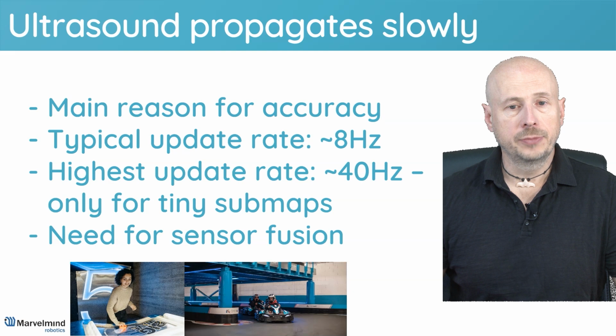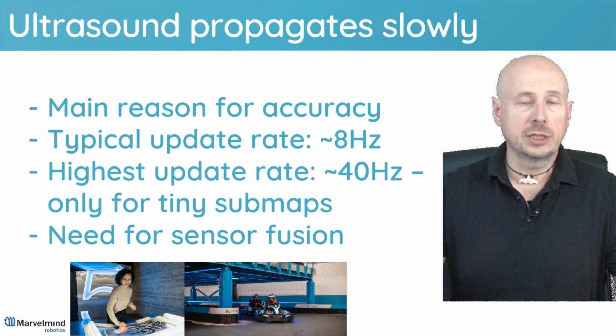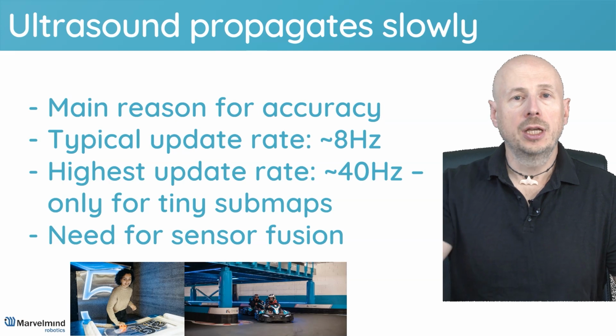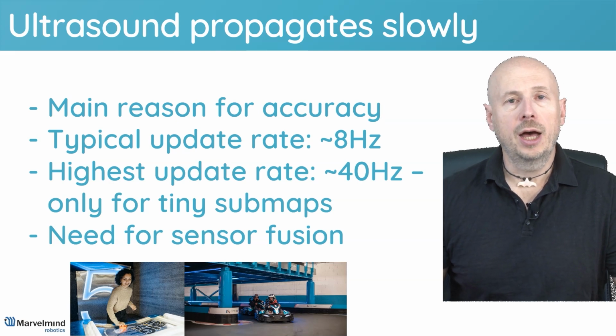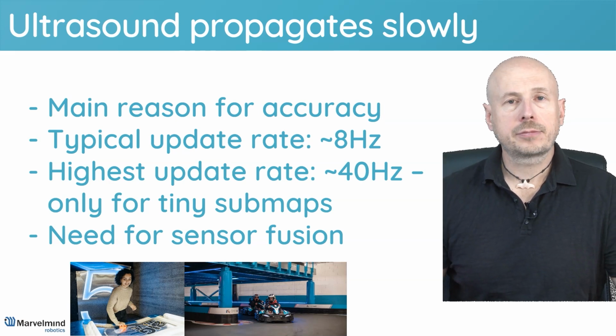which is enough for even very fast moving mobile objects. And it's almost impossible to achieve by ultrasound, because once again, return back to the basic calculations. 340 meters per second divided by a 100 Hertz update rate, so the size of the map, even theoretical, would be just 3 meters, which is tiny.